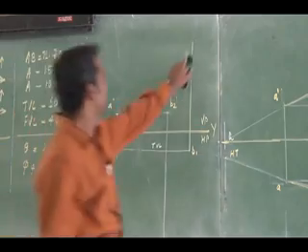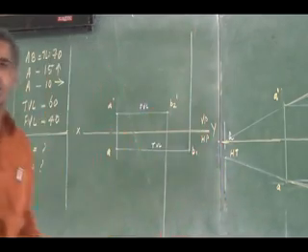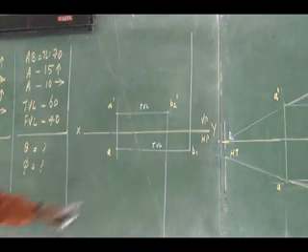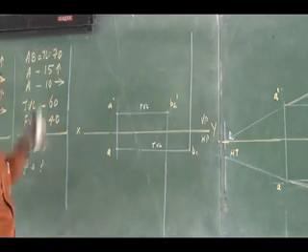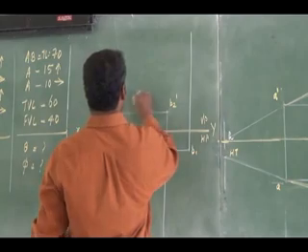To use the true length and find the true inclination theta, which one do I have to connect? A dash and I have to get the B1 dash. What is the true length? You have to use the true length as 70 mm. So I can use 70 mm.